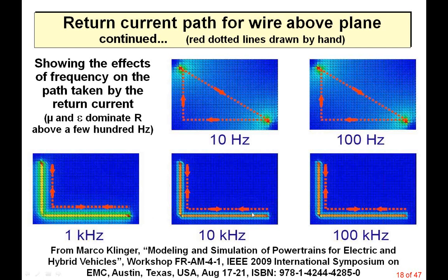At 10 kilohertz, all that happens is the current sucks itself in a bit tighter, and at 100 kilohertz, we're down to the resolution of the calculation cells used in the simulator. I've seen this done up to 10 gigahertz, where all that happens is the line gets dotted because of the wavelength. Dashed, I should say.